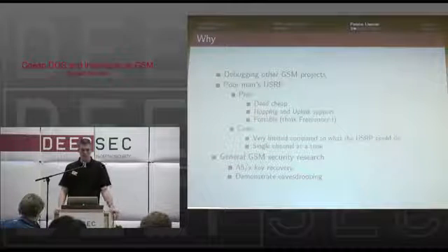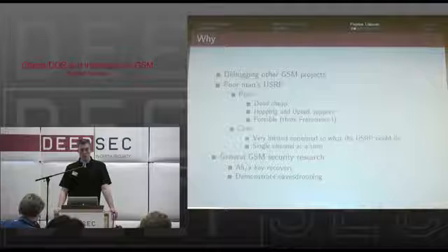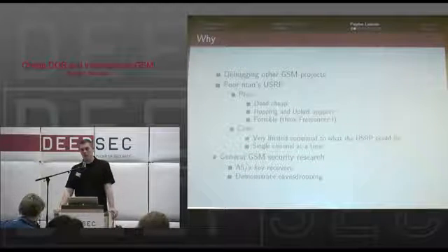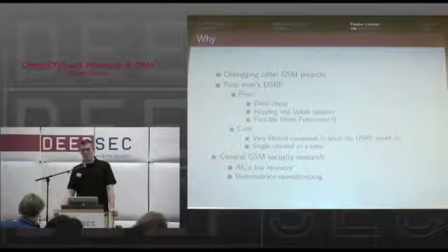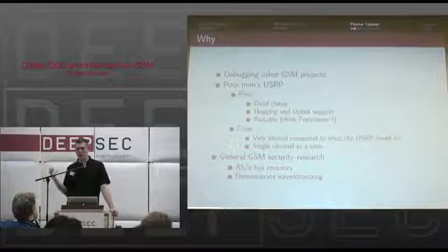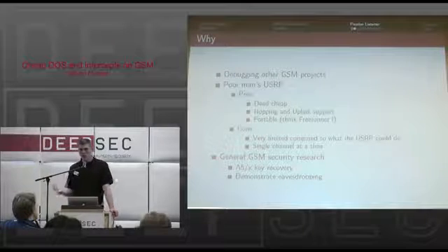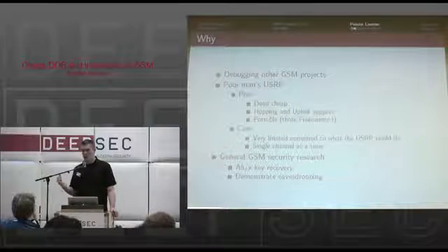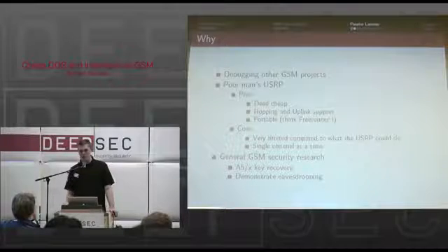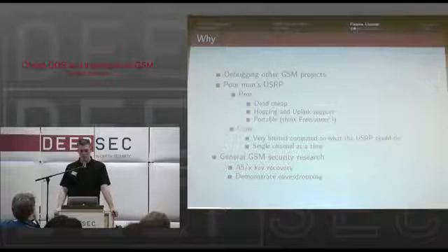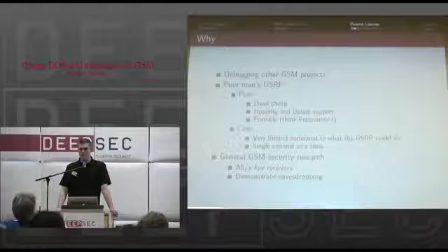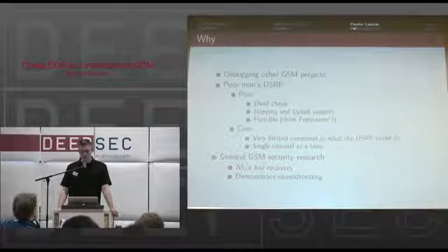Of course, it's kind of limited because the USRP is basically a wideband software-defined transceiver. It can do much more than what the phone does, but the problem is it's also much harder to code because you basically have to code everything yourself. For example, what's currently coded in AirProbe, in particular the demodulator, works, but it doesn't work as well as the commercial demodulator in this phone that has been optimized for many years. So in general, everything related to GSM could use a cheap sniffer.